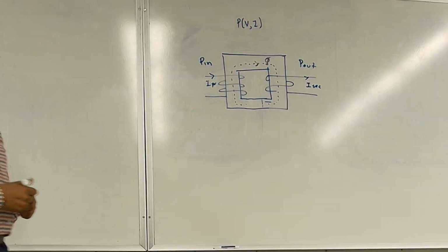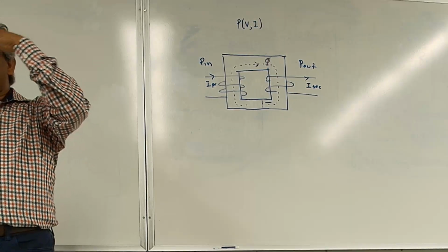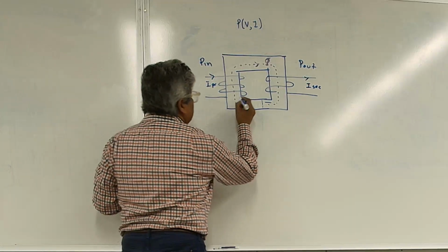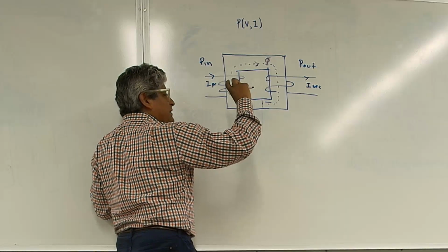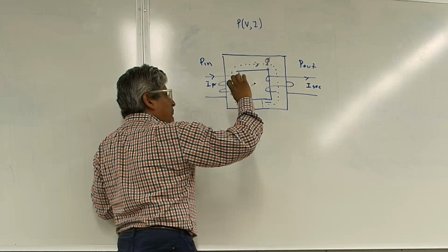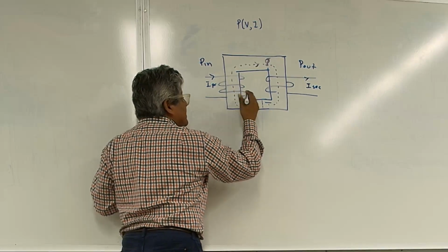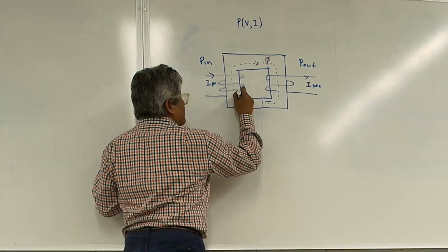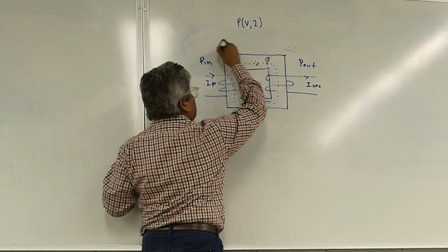Now, remember I was telling you about the spacing of the sheets of lamination in the transformer, the geometry, how precise it is. If the geometry is not as precise, it results in the flux lines going into the air, escaping, especially on the corners, okay?